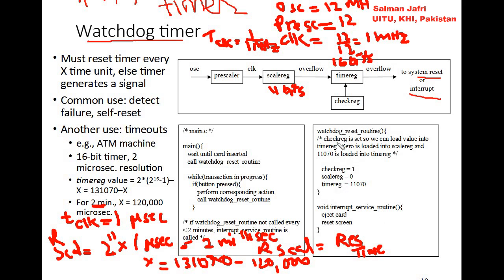And what happens if this watchdog_reset_routine cannot be called? We call the interrupt service routine, which ejects the card and resets the screen. So that is all about the watchdog timer application.